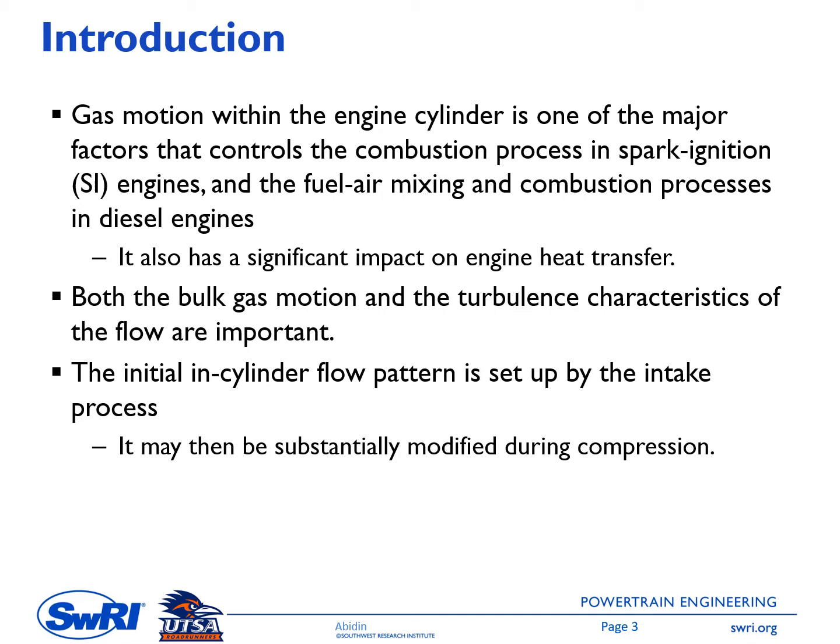Gas motion within the cylinder is one of the major factors that control the combustion process in spark ignition engines, and the fuel air mixing and combustion process in diesel engines. It also has a significant impact on the engine heat transfer. So you'll have a certain type of charge air motion entering the cylinder that will control the bulk flow during the intake process, compression process, and thus continue to the expansion process. This bulk flow will determine the flame propagation.